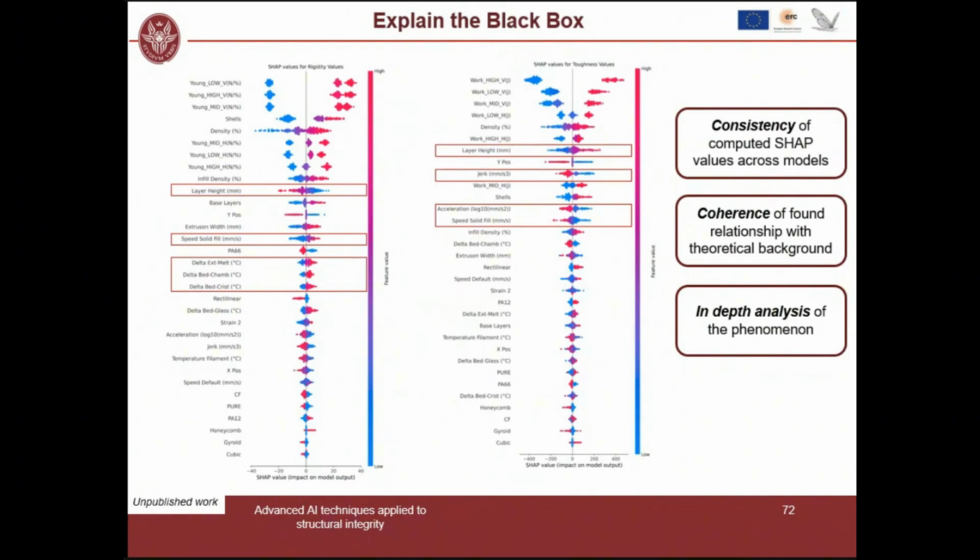So here we see, of course, that the toughness increases if we lower the instances of defects, because with a thicker layer rate, I have fewer interfaces, so I have fewer defects inside the specimen, and by slowing down, there are fewer defects in my materials. So that makes sense, this explanation.